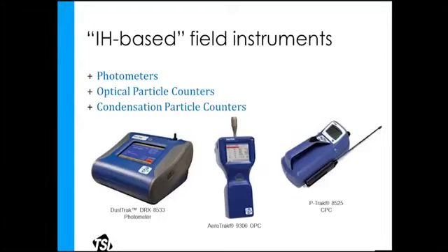So here's a good trivia question. If I had a poll thing, I'd do that again. What OSHA exposure limits are based on condensation particle counting? So number counts. It's a trick question because there are none. They're all based on mass. So the P-Trak doesn't measure anything compared to an OSHA reference, but it counts numbers of ultrafines. So it's an interesting tool to use for a certain thing.